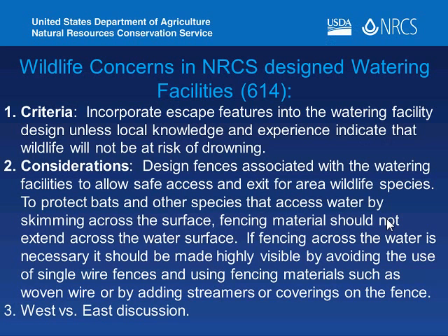We did want to talk about wildlife, as Bill mentioned. It is in the national standard. Here's some excerpts from the national standard. So the first one is in criteria. So criteria is not optional for us. When we're doing planning, we want to incorporate escape features in the watering facility design unless local knowledge and experience indicate that wildlife will not be at risk of drowning.